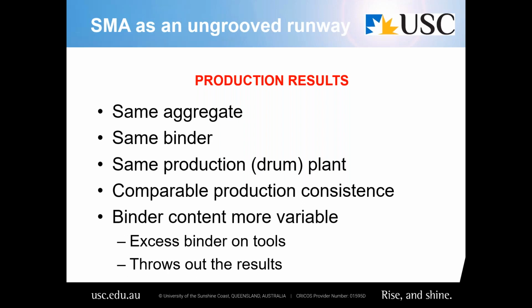And then if you get that wrong, because it's essentially a manual process and it's all sticky and gooey and a mess, and you put a bit too much bitumen in that sample and not enough over there, and then you test that one over there, it'll look like it's devoid of bitumen. But it's really a testing issue as opposed to an actual difference in the material that was being produced.